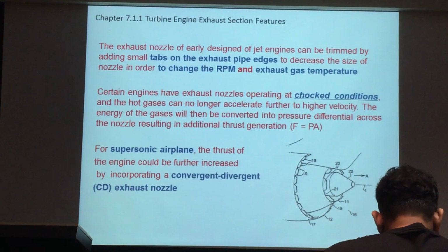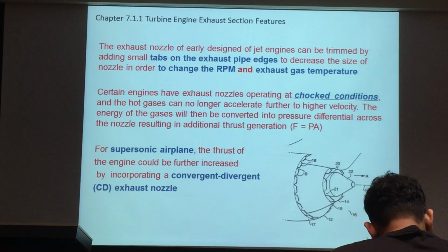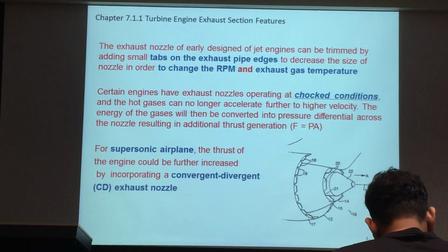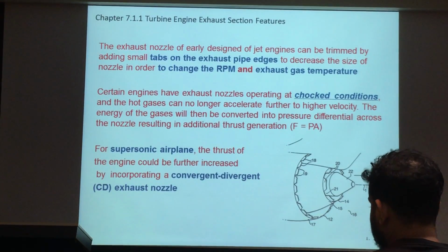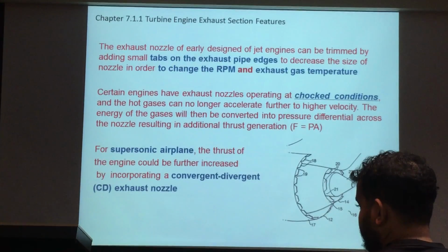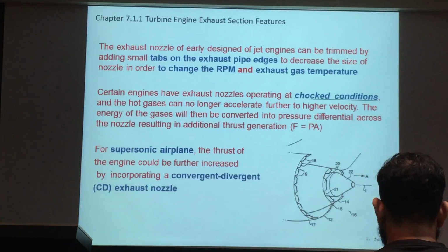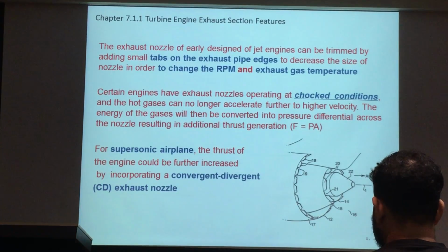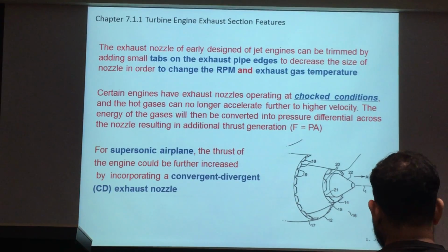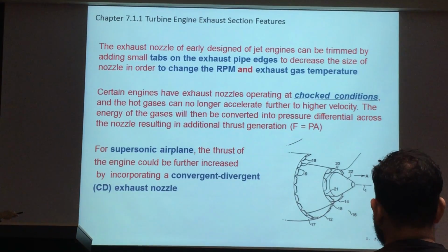Remember, at different aircraft at different speed, you have a different nozzle area for the military aircraft. Because for commercial aircraft, doing this is not efficient. Doesn't gain anything. That's why they remove it away. But for military aircraft, yes, because the speed range is wider. You need to have a change in nozzle area. To change a nozzle area, you got a side effect. What is the side effect?